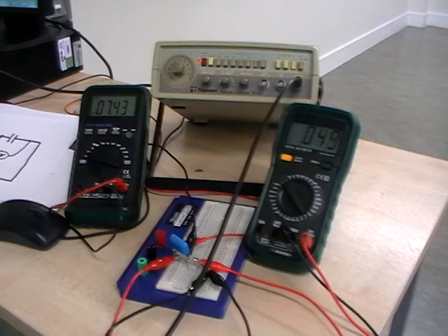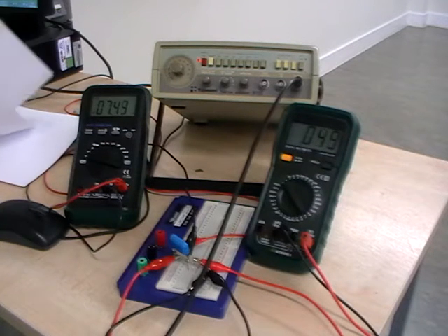What I find is that suddenly the capacitor behaves like it's got some sort of dynamic resistance. The higher the frequency goes, the lower the resistance of the capacitor. Now, we don't use the term resistance for that, we use the term reactance. Why do we use the term reactance? Because a capacitor, and also a coil, but in opposite ways, react to an alternating current by changing their resistance. Reactance, the symbol is X, and we measure it also in ohms, just the same as resistance, but the only difference is it varies with frequency.